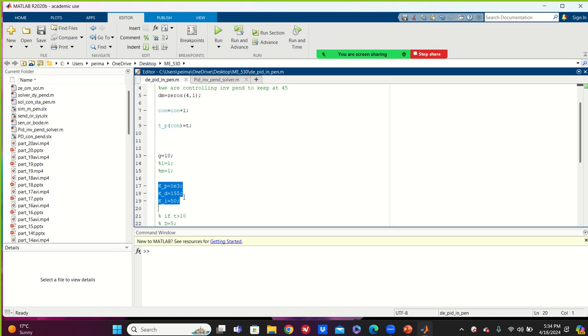I'm going to show it now between shortening the transient response and the control command or torque in Newton meter. You have to be very careful, because in reality, when you apply this to a robotic problem or whatever it is, maybe your actuator that sends the control command becomes saturated very easily, or gets damaged. This is out of range of the torque.